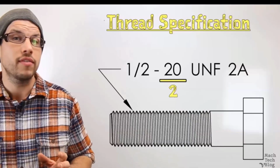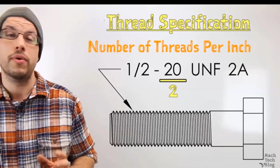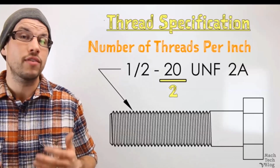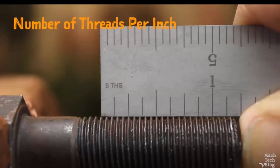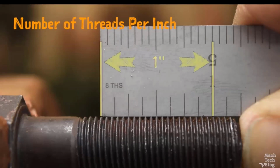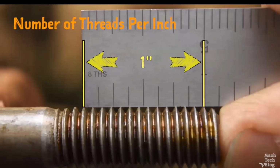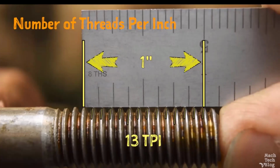The second piece of information is the number of threads per inch. This is dependent on how closely the threads are spaced as they're wrapped around the cylinder. You can measure the number of threads per inch simply by laying a ruler over the tops of the threads and counting how many crests there are in 1 inch. Our bolt has 20 threads per inch. This other bolt has the same major diameter, but there are fewer wraps of the thread in a 1-inch segment. In this case, there are only 13 threads per inch.